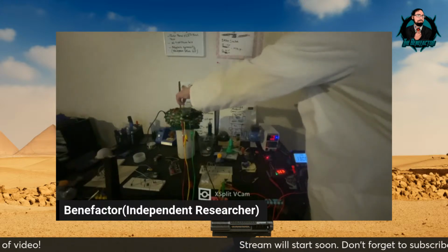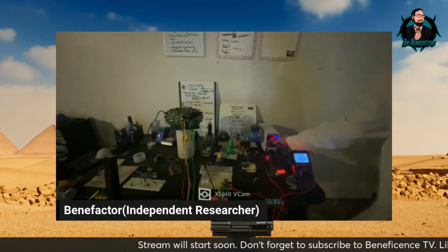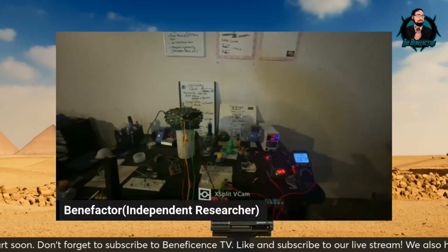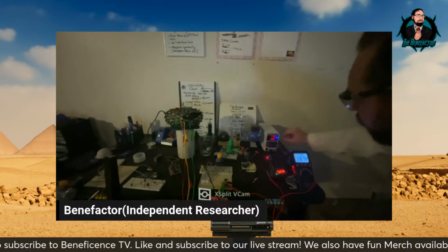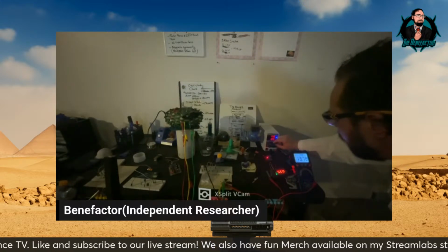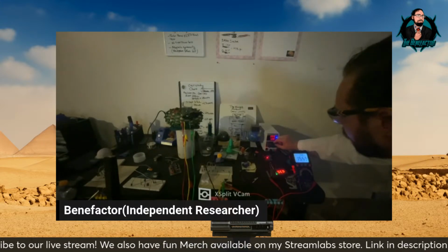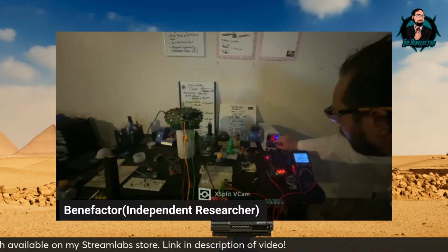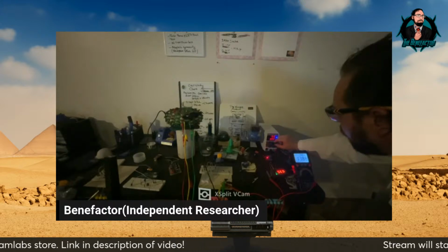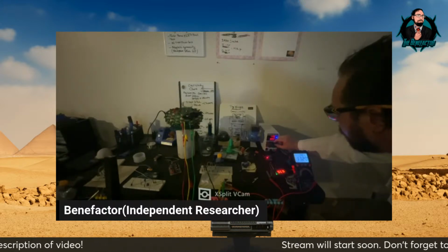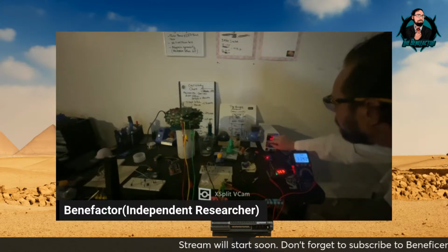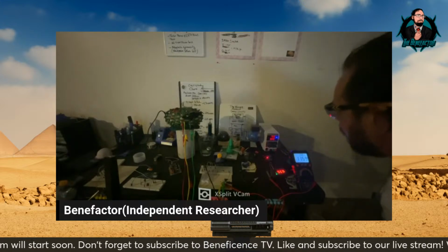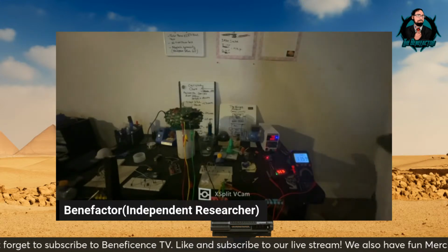Is that magnet moving? No. We're at 11 volts. No, how many amps do you have? 1 amp and 17.9 volts. That's 17.9 watts. So turn down your voltage a little bit and don't go over 3 amps. Okay, so we're at 15 volts. 18 watts ain't going to burn that supply. 15 volts, 0.88 on the amps. It's a 50 watt supply. Yeah, okay.